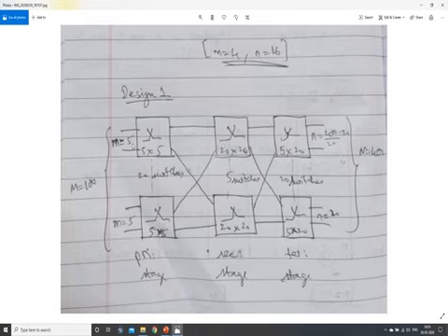So here m is equal to 4 indicates that there are 4 inlets, and these have to be divided for the 100 incoming trunks. So 100 divided by 4 turns out to be how much? There are 25 primary switches. Now what does this 25 indicate? That the number of inlets to the secondary switch should be 25. So since this was 4, the switch size we consider for the primary stage will be 4 by 4, and at this stage the switch size will be 25 by 25 for the secondary.